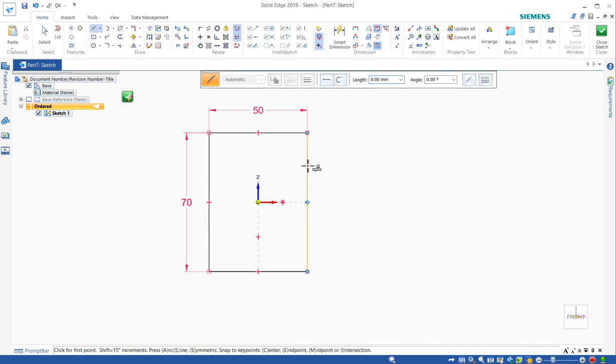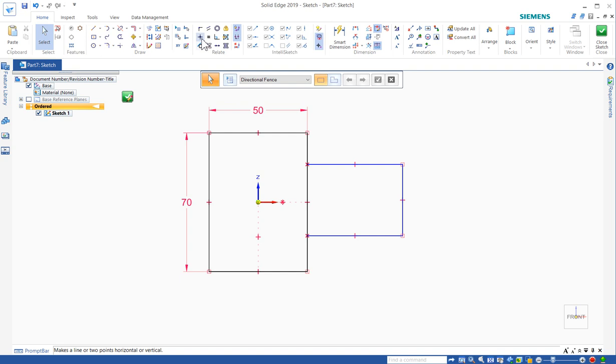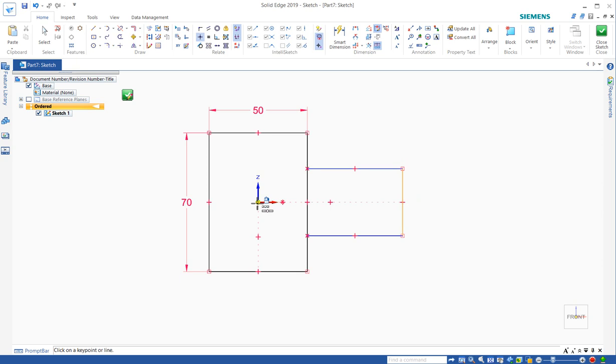So let's continue with our little shape. I'm just going to kind of draw visually and randomly, but I'm going to focus on getting things kind of square by using my IntelliSketch, and I'm just going to kind of eyeball this. This is a really productive workflow, I believe. And notice that those elements are blue. So we can manually apply a horizontal relationship. This time go between key point and the center. Creates a horizontal alignment, so we know that is exactly on center.